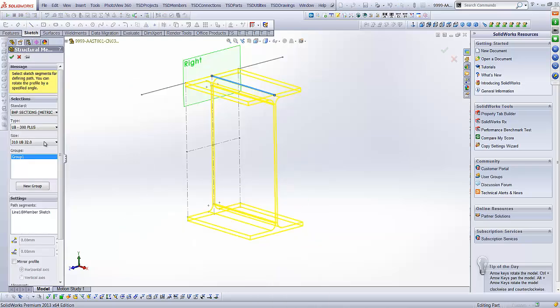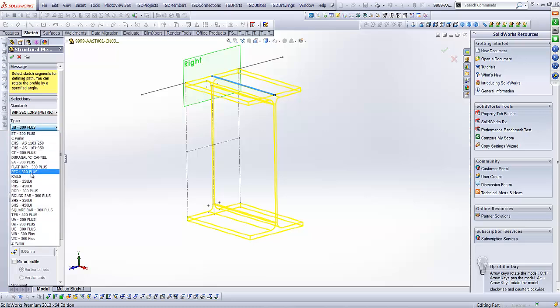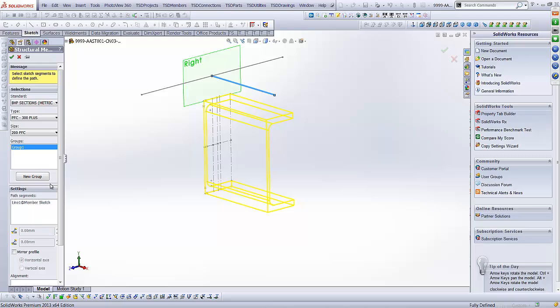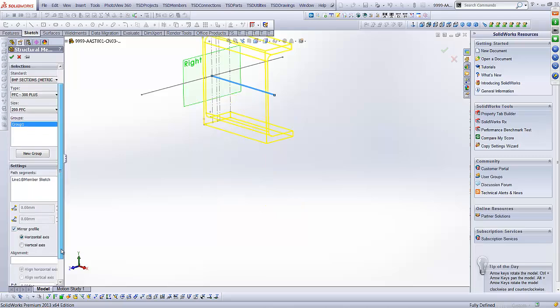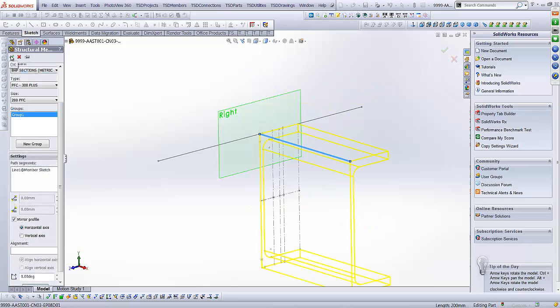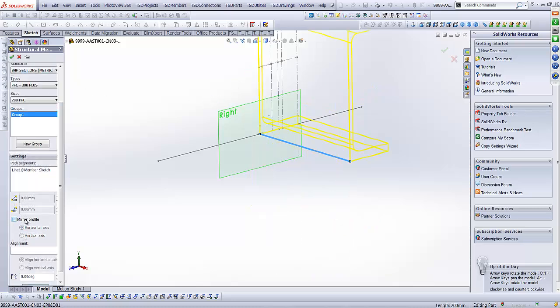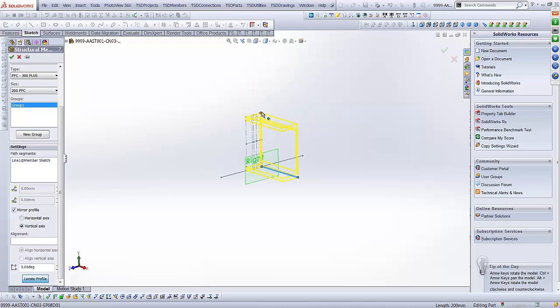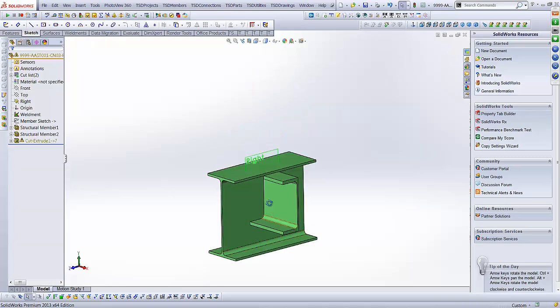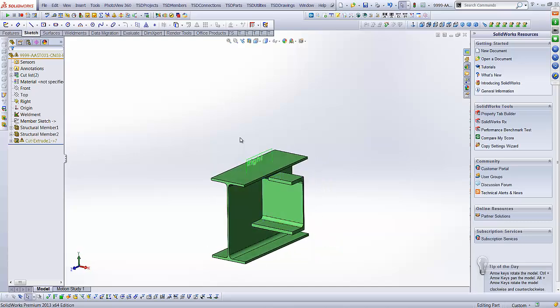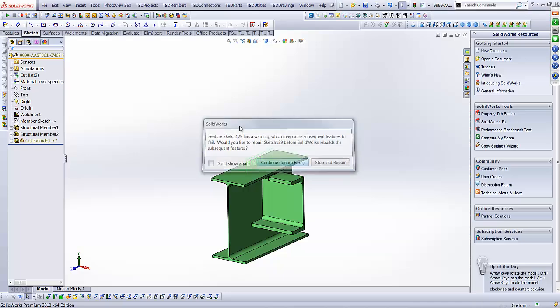And then I'm going to change the section to a different one, and I want to make it the same as what we have in our sections. Okay, and in this instance I'm going to have to mirror the section and set it at its right location. Now if I mirror it, I need to go vertical and make sure that I've got that right in my selections, and pick the top point, and now I've got my section in the right orientation. Now you'll notice the cut is still broken here. We're going to work on that one, so I'm just saving it.